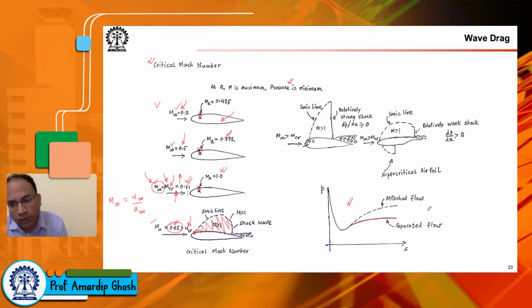So if you do not remember our discussion of pressure drag due to flow separation, you can go and take a look at this discussion, because of course, these wave structures are dissipative, and power from the engine is getting wasted in these wave structures. But at the end of the day, this drag force should be obtainable from the pressure distribution on the wing surface. Okay, you go at each point, you find the pressure, you find the force, you resolve it into components along the relative wind, normal to the relative wind, etc.